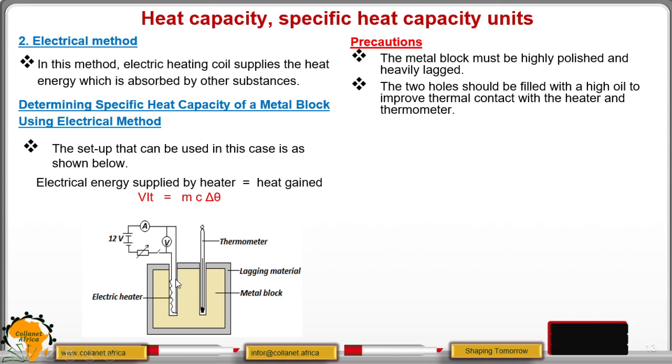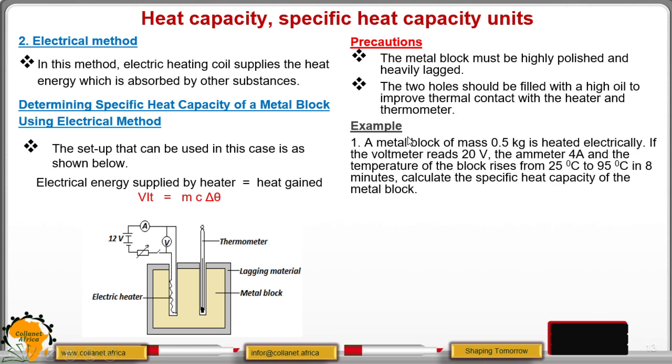Remember, we have the two holes inside the metal block. You must ensure that these holes are oiled, as this will improve the thermal contact. Then we look at an example here.